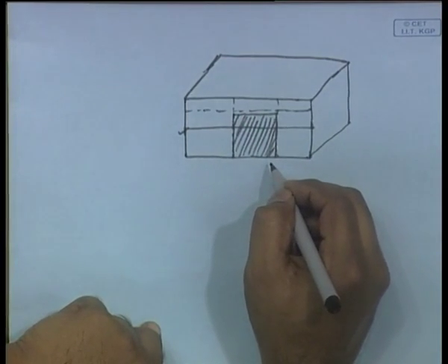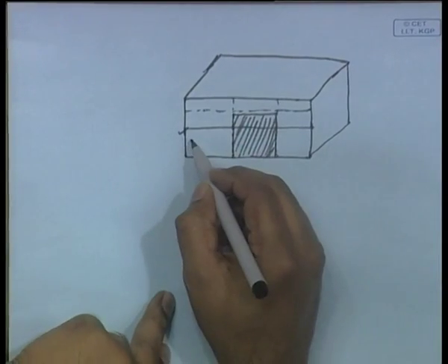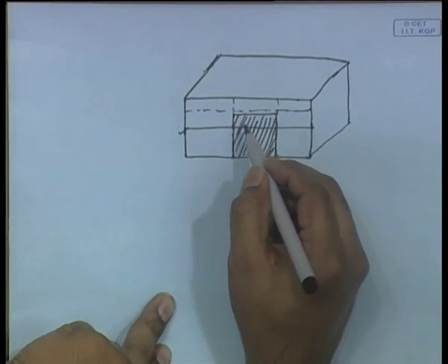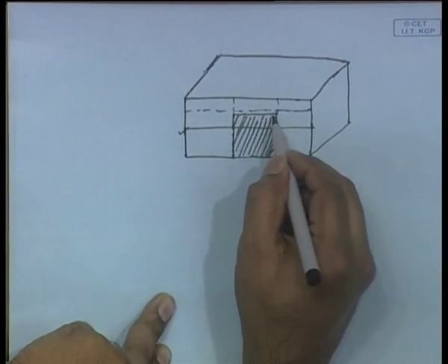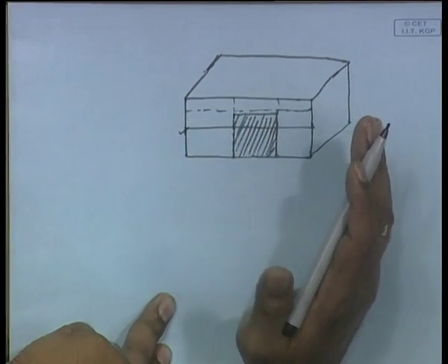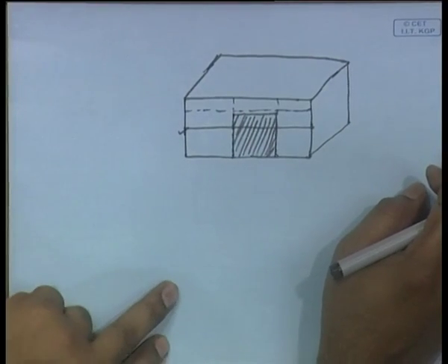But the second possibility in this problem is when your draft is above the flat. That becomes slightly different, because bilging then occurs only up to some point in between, and some part of that compartment is still remaining. Therefore, it becomes slightly difficult to calculate the volume, I, etc. So, that is the only thing in this problem. So, let us check that.